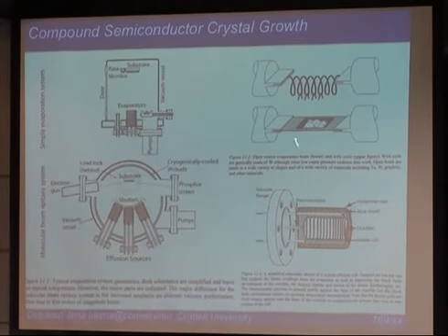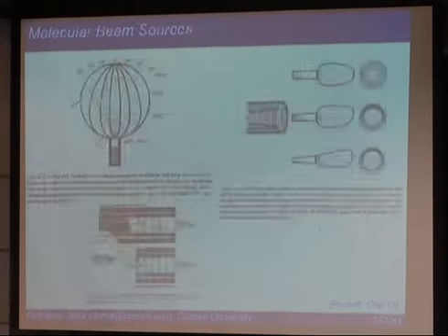I mean, obviously this one goes only upwards, not downwards, but it doesn't have this collimated behavior that you have with the MBE with these sort of effusion cells. Makes sense. So this thing will deposit everywhere on the walls of the system. And for example, when we are doing, instead of crystal growth, when you're depositing metals for contacts in a transistor or a laser, when you deposit metal, you could use a thermal evaporator. This would be basically a thermal evaporator, or you could use an E-beam evaporator.